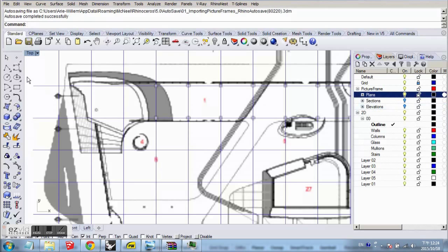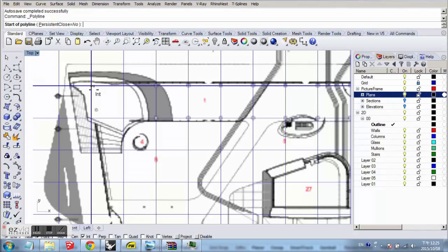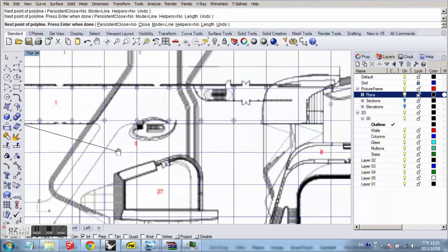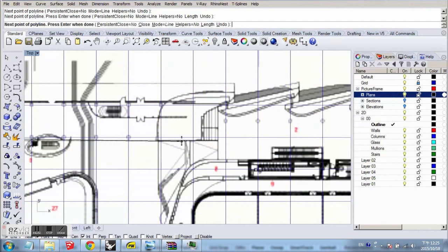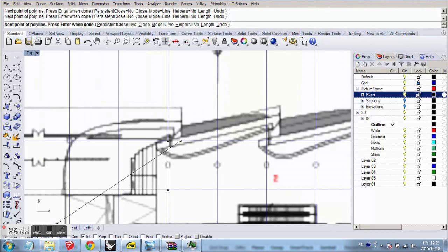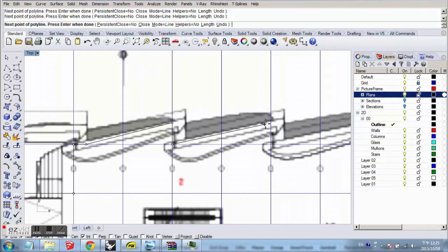You can hold Shift to temporarily toggle the orthogonal option in Rhino. Alright, so you can see on the ground floor image, the part here is quite wavy. We'll simplify the floor outline a little, so it will be more like a saw zigzag. We'll use the grid and smart track to standardize the dimensions of this part as much as we can.